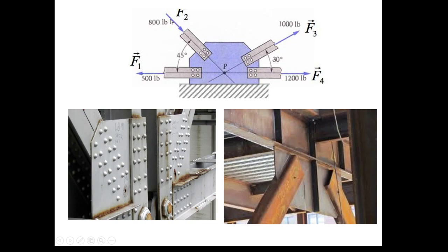the force acted by the member onto the joint, it is a resultant force, of course, okay, is to be coincided with the line. It joins the centroids of the cross section of the member. How many cross sections can be defined along a structural member? Theoretical answer, infinite number of cross sections. Okay? If the resultant force has its line of action coinciding with the line, it joins the centroids of the cross sections of the member, yes, we can say that when you position the member,